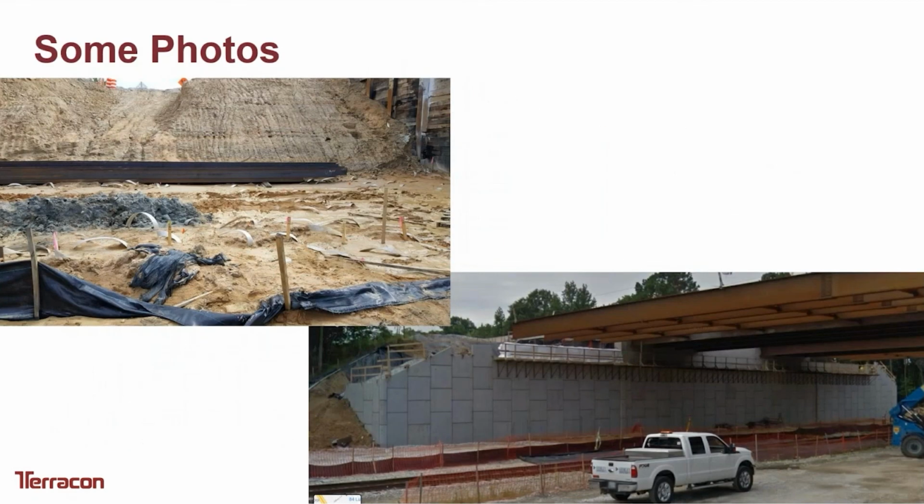I included a couple photos. This photo shows the wick drains, how they're installed, and you can see there's a filter fabric material at the top, and they also need to place gravel at the top of this so that it serves as a drainage layer. And you can also see the corner. If you remember the corner that I showed you for this wall, it is not completely constructed yet, but at least they constructed the MSE wall on this side.